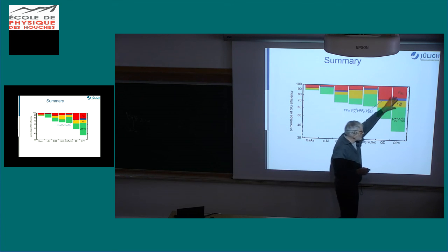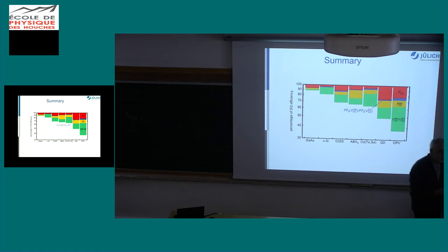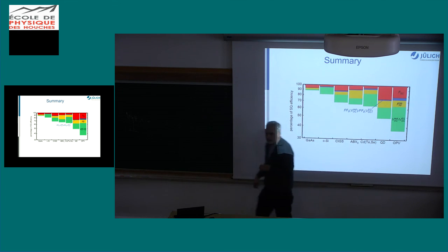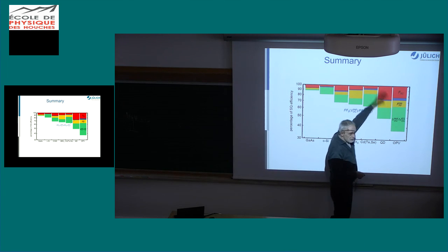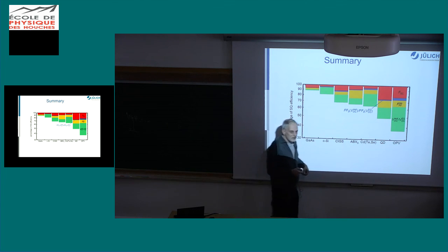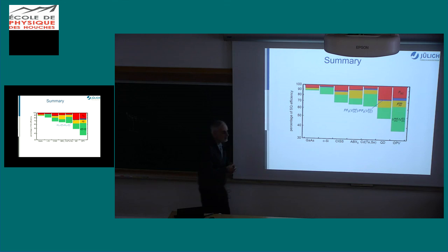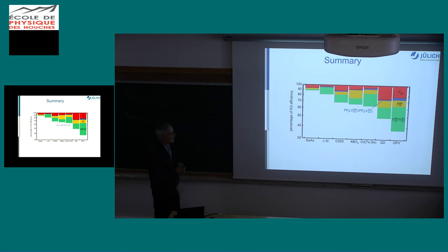and I have to say, okay, the efficiency is a product of JSC, VOC, and fill factor. And so the losses are also products. But if you have products, you cannot add them up. But you can add them up if you choose the logarithmic scale. So regardless of how you place those blocks, it is always correct. So the size is really the size of the loss.